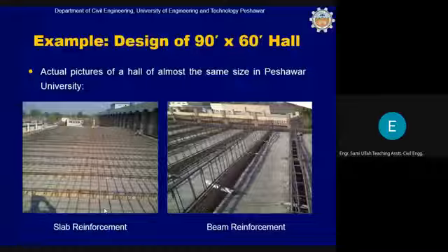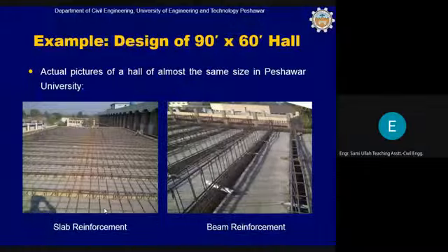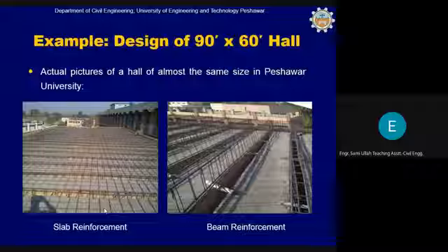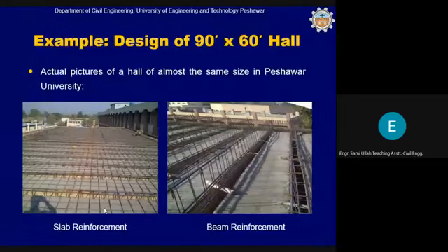Okay, I can show you the comparison once again. If you look at this slide, can you see the slide? With 10 feet spacing, the slab thickness is 4 inch, but you have used 6 inch. So further reduction in this will not change this 6 inch slab.